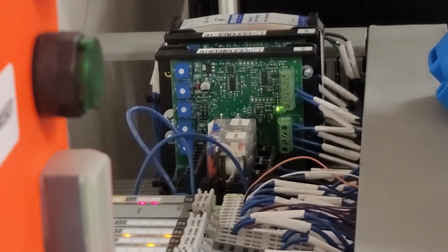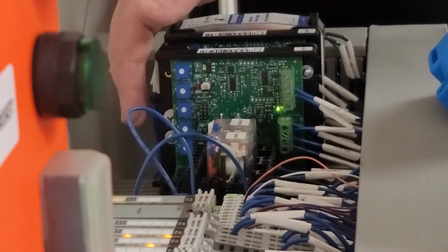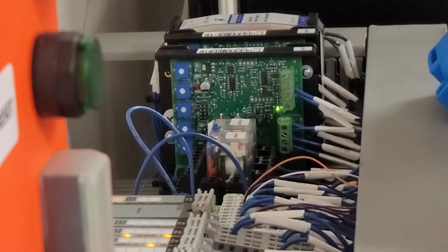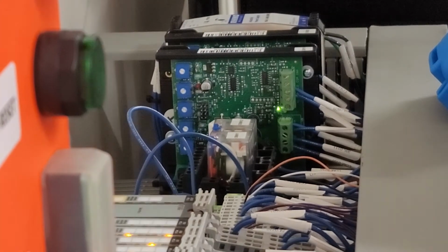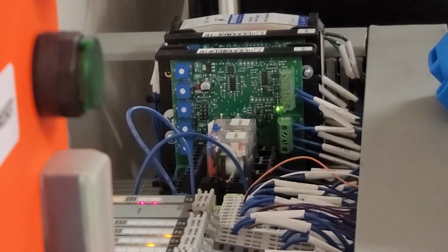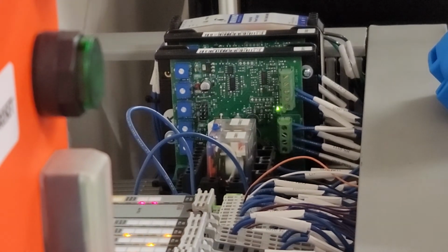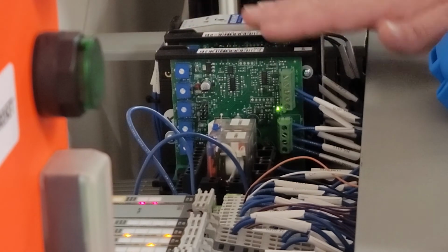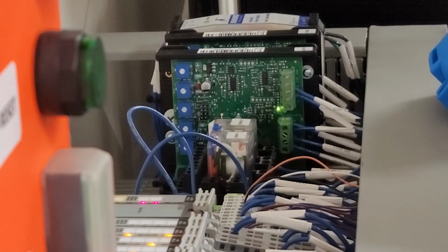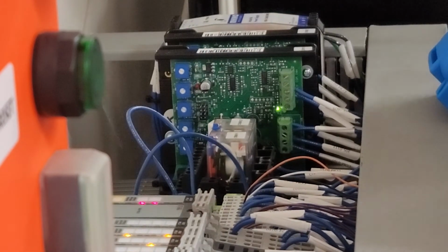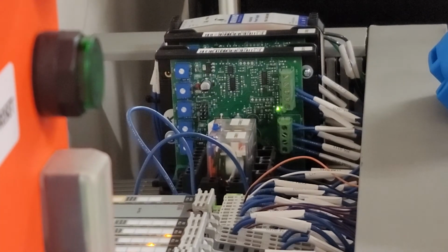and I also believe there's a minimum speed set point, and there is an acceleration and a deceleration. The one that I am interested in seeing is our maximum speed set point. If it's not quite set all the way up, then I'll have to change that, because we don't really want to make the drive care about the output voltage. We want to be able to control that directly from the program.